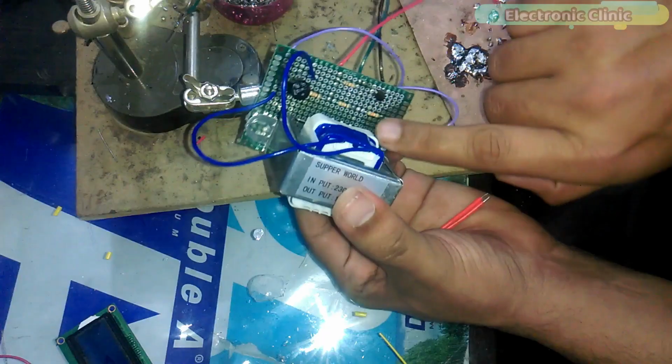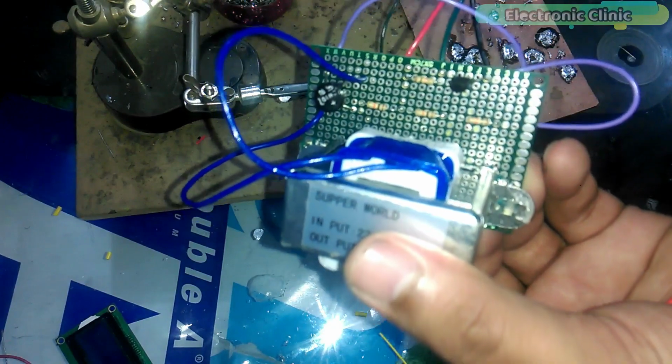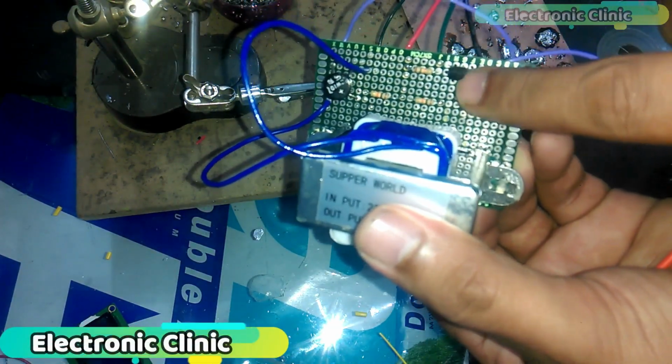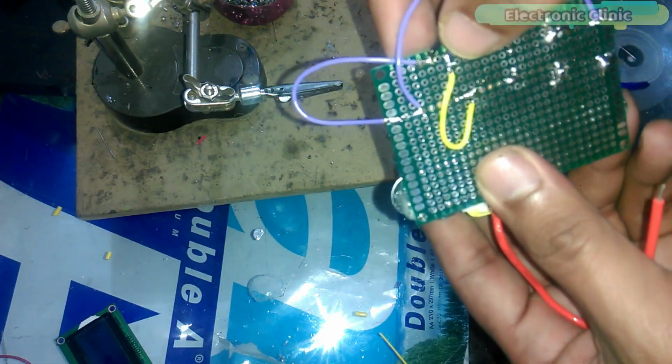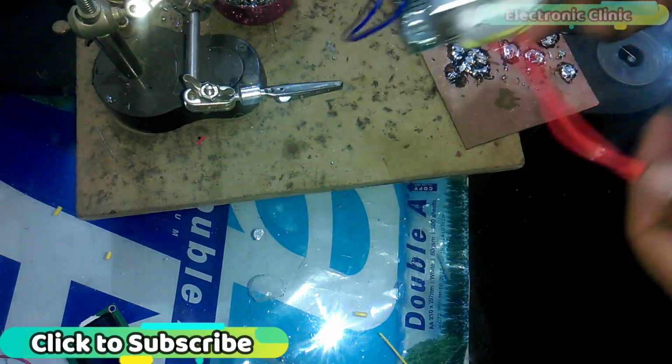One last connection. Connect the base of the 2N2222 NPN transistor with the voltage divider circuit. I just connected a wire from here with the base of the transistor. So now our soldering is completed.